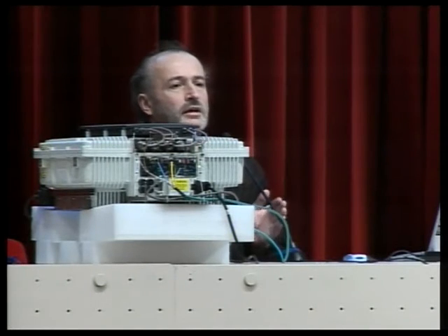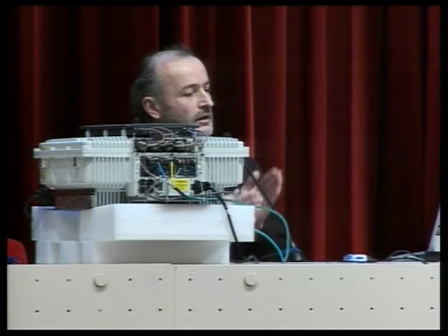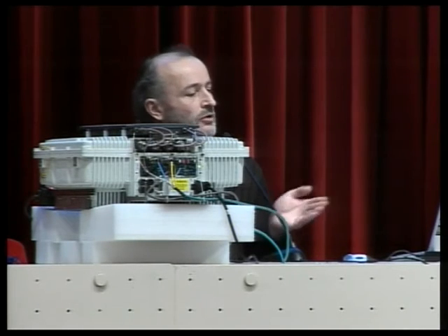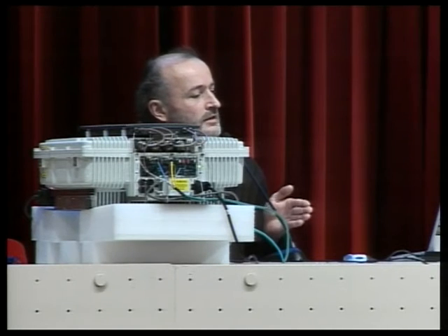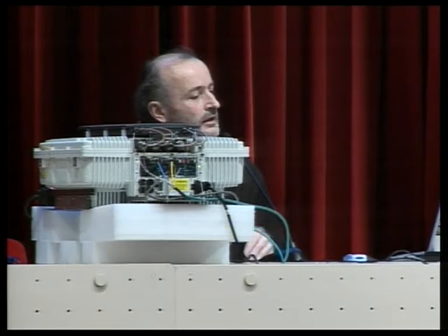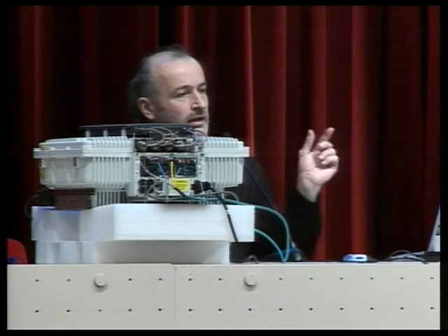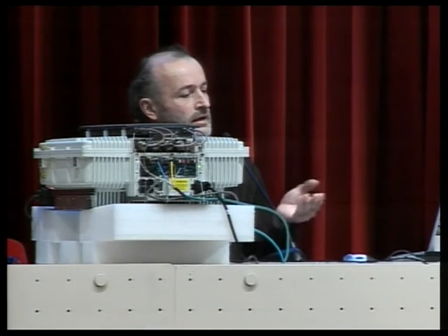The speech and data traffic is usually divided in the time slot in 4 different subslots. Basically, you don't need the full weight of 64 kilobits, so you divide it in 4 subslots with 16 kilobits each. This division is very simple. You take the first 2 bits for the first subslot, the next 2 bits for the second, and so on.